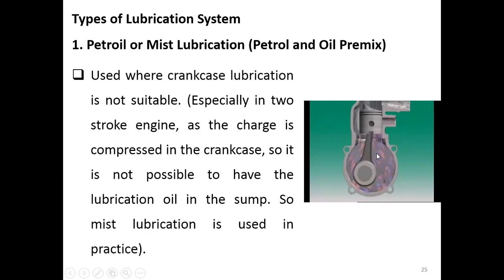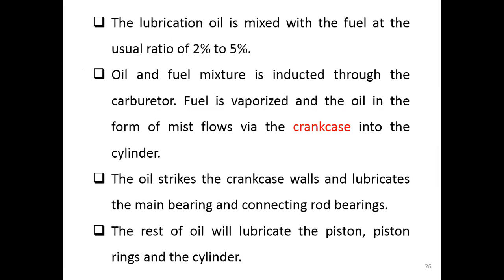For a two-stroke engine, normally we don't have the oil pan, because the air fuel mixture is normally compressed in the crankcase. So it is impossible to have lubrication oil in the sump down here. That's the reason why we have to mix the oil with the fuel, especially for the two-stroke engine.